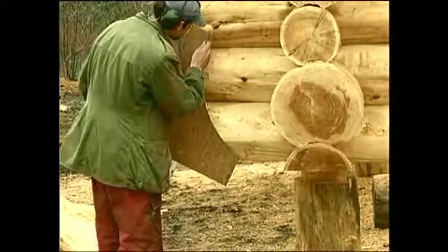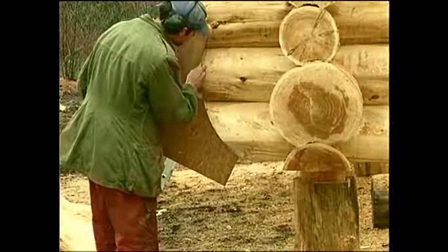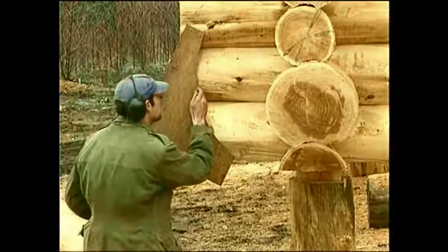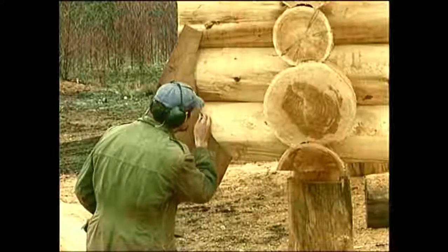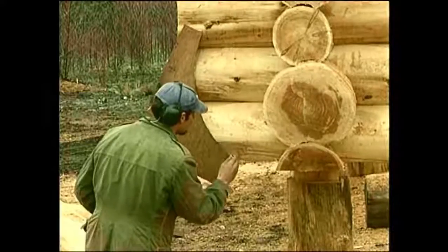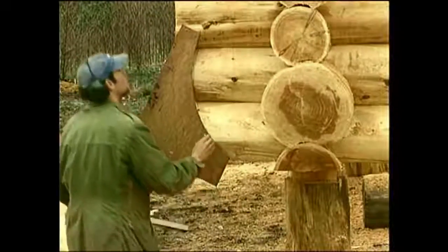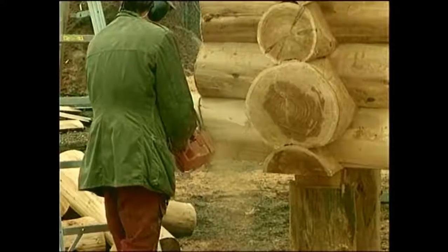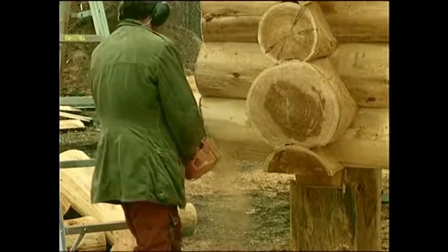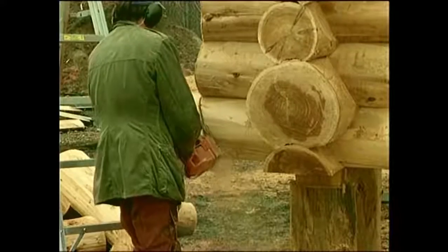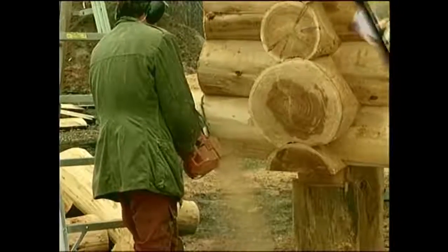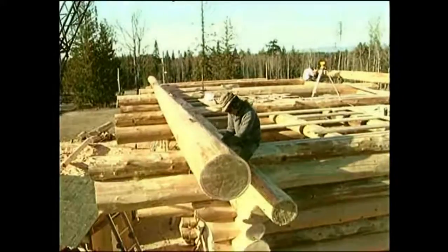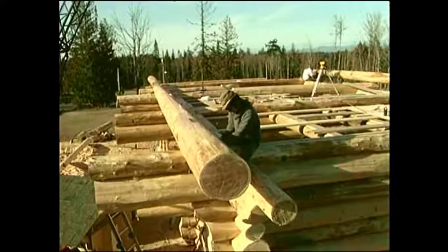2. Cut the log ends to the design and profile that you choose. And 3. Finally sand the log ends and openings with first 36 grit then an 80 grit paper. At this point, your log house shell should be complete.